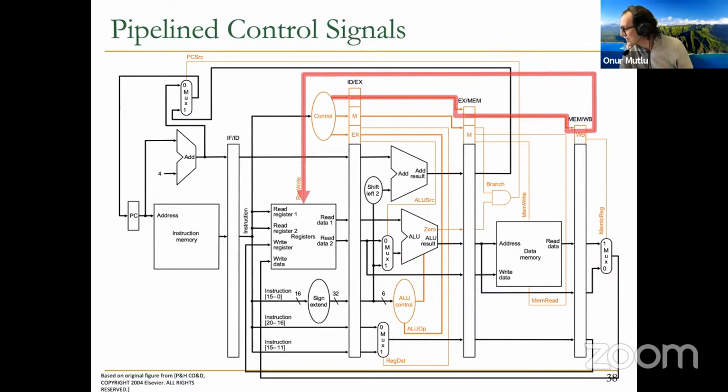If the branch condition is asserted, what happens to the skipped instructions already being processed in the pipeline? That's a great question. Basically, if branch is supposed to be taken, and if you already fetched some instructions into the pipeline, what happens to them, right? It depends on which instructions you fetched into the pipeline. If you have not done branch prediction, which we will cover, and fetched the wrong instructions, you need to basically get rid of them. This is called flushing the pipeline. So we're going to talk about that in more detail.